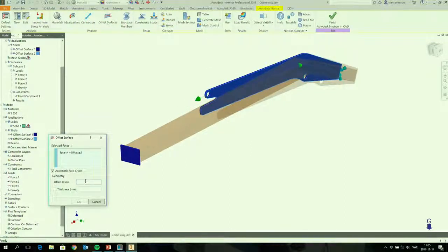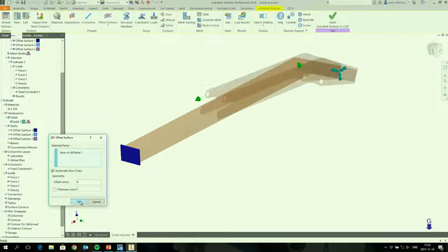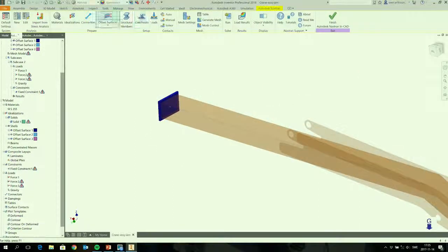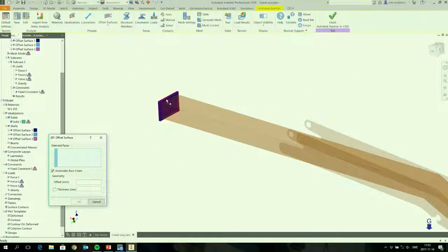And it's 2 reasons. One is I want to show it, and the other one is that if you connect a shell element to a solid, it will be a hinge that you may not like to have, or hopefully you will not like to have it. So you need some kind of a shell on the surface as well. And we take that last one as well.